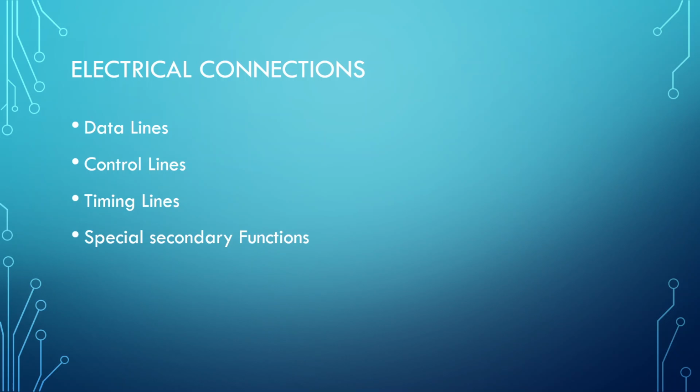And the control lines, this is, as far as I'm concerned, when things start being a bit more complicated. Oftentimes, if you get into the world of TTL serial, all you do is ground, transmit, receive. 3 wires, you're done. All you need to know is there's data coming in, I need to be able to send data out, and I need that ground, that 0 ground rail, whatever you want to call it, to have a complete loop. As long as I've got those 3 lines, I can talk to other devices. In the world of serial, it's not quite that simple for RS232.